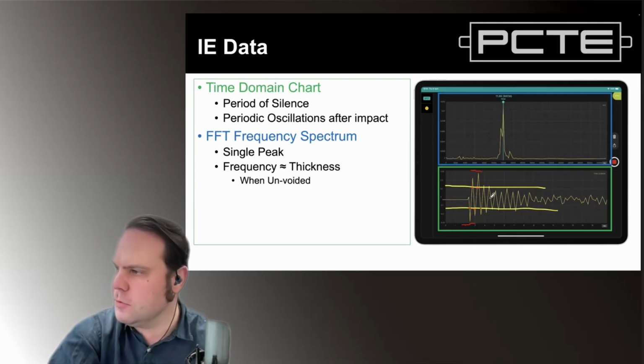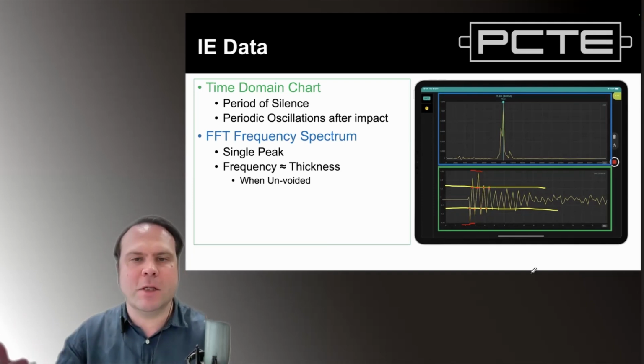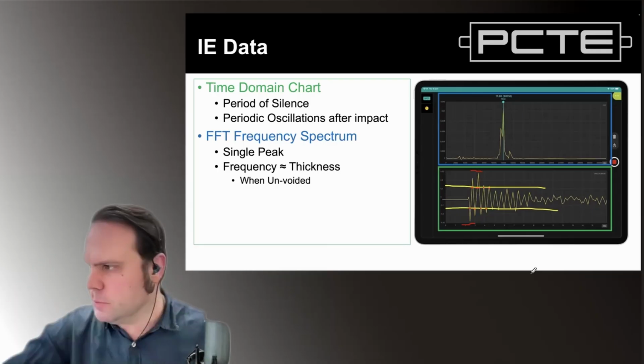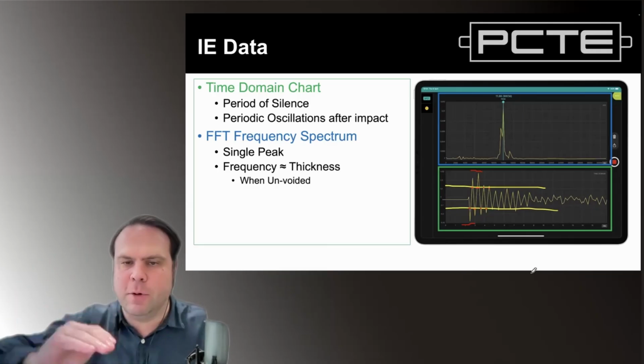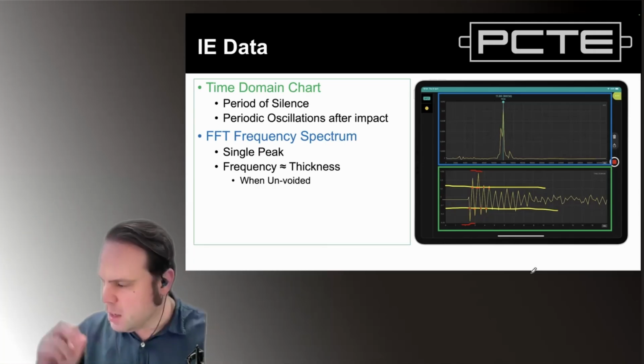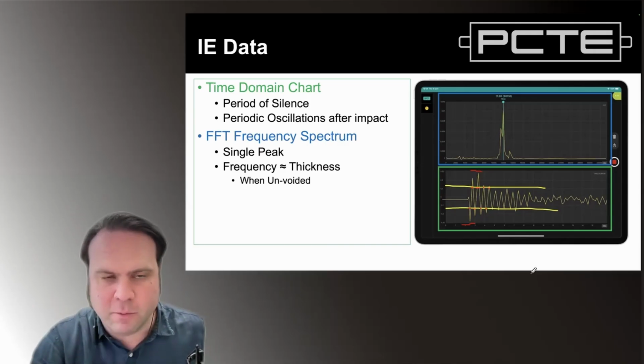This is called clipping. You've heard this if you turn your speakers up too much on a sound system, as it goes all crunchy and horrible sounding. So if we're going to be doing frequency analysis on this result, to overgain, to push our input above 100% or below negative 100% of the scope of the test, ruins the result.